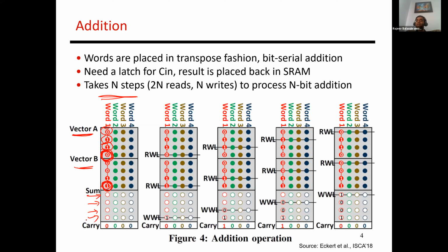Not as much reading and writing out of registers, which is kind of what we had said would be very valuable, right? So when we discussed data flows, we basically said that there is this hierarchy that feeds the MAC units, and you ideally want to get your data out of registers and maximize reuse. If not, then you go to the next level, which might be a few kilobyte buffer. If you can't find data there, then you go to the next level of the hierarchy, which may be a few hundred kilobytes or megabytes, and then finally DRAM, right? But over here, you'll see that all the operations are being fed with these SRAM reads and writes, which are a little bit more expensive.